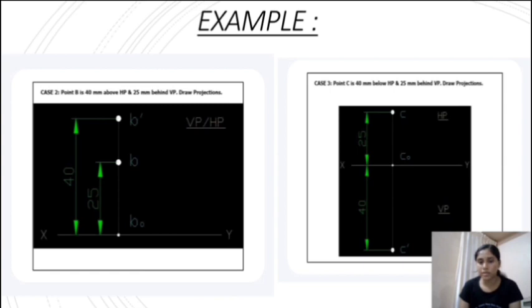You can see a 25 mm line there, and in the next projection you can move the cursor to the point where the first starting line was, and then you can give the length as 40 mm and angle as minus 90 degrees and press enter. You could see a 40 mm line there. Use smart dimension and draw the points, top view and front view.